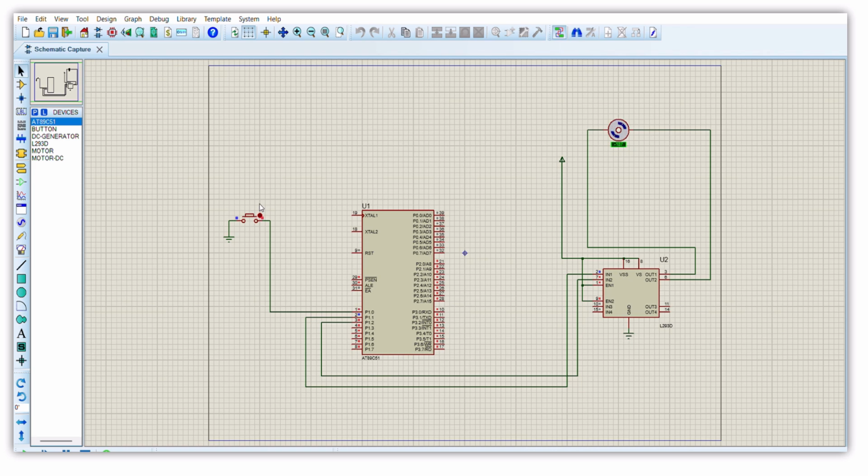So when the button is released, the input at port 1.0 goes low, that is logic 0. So the microcontroller detects this low signal and it can do nothing if no action is programmed for low input. So when the button is pressed again, the microcontroller receives the signal, causing the motor to rotate in the opposite direction and thus locking the door again. And so this process continues.